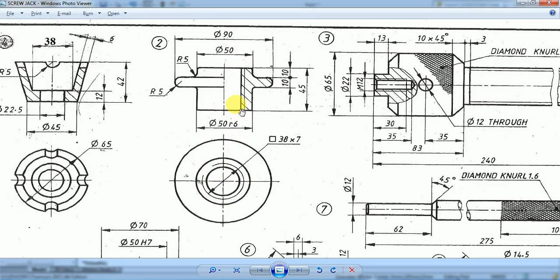Okay, so whenever the component is hollow cylindrical or cylindrical, we are again going to use the revolve option. When we want to use the revolve option, we have to create the profile of the body, meaning the profile of the component which is present towards one side of its axis. In this case, this is the axis of the nut.